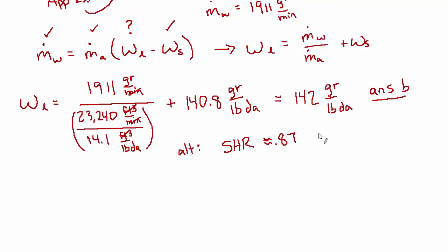And then if you're using a version of the cycle chart that has that little protractor thing on the top left, then that tells you the slope of the process line for some combination of sensible and latent heating. So let's suppose state 1 were here. I'm just picking this arbitrarily. Then there's this latent and sensible load in the room, so it would be up and to the right to some point, which we would call state 2. And then you could come down.